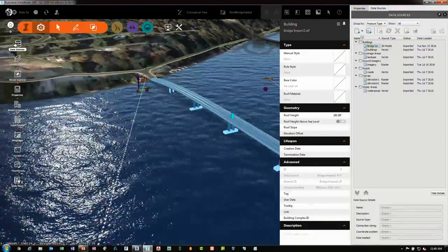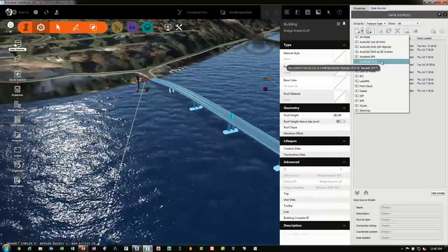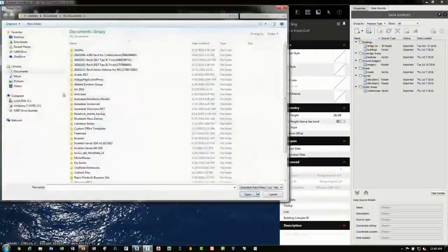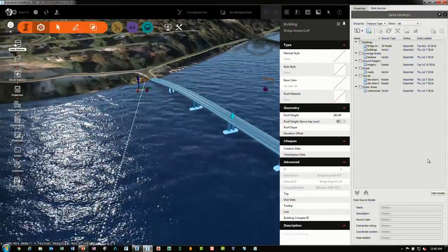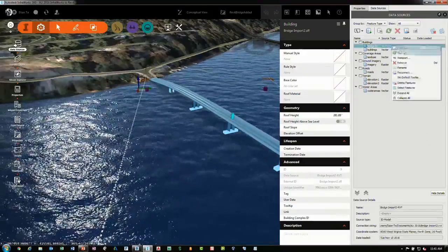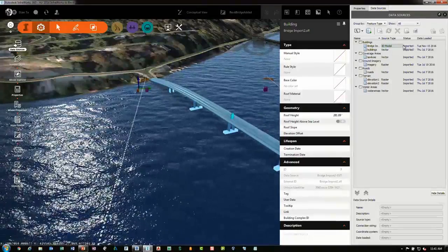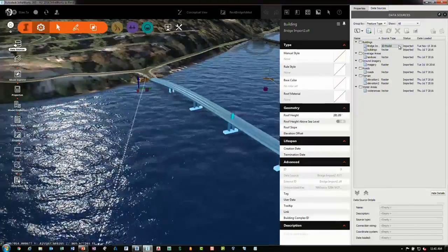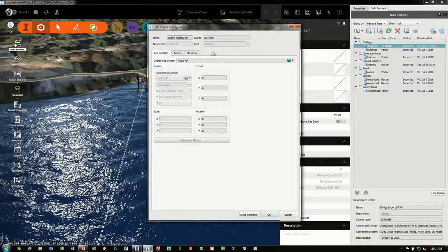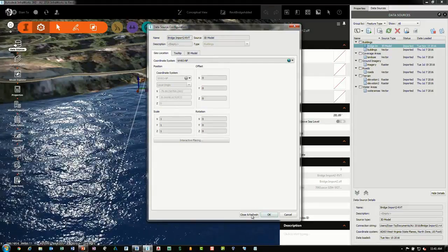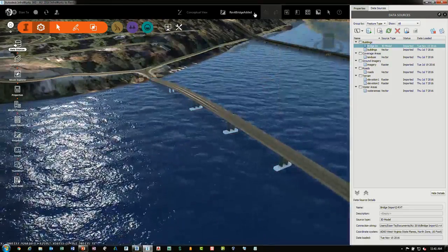To bring in the Revit bridge, the Revit file back into InfraWorks, I can just select Autodesk Revit and go get the file, browse to it, get it selected, bring it in. Or I can just use Windows Explorer and drag and drop. And once you do this, over here it says under status, it'll either say configured or imported. By default, it will initially say configure. And so you'll have to go into the properties again here to make the necessary adjustments. And then once it's imported, you can click close and refresh, and the data will show up accordingly. If we look at other file formats that were brought in,